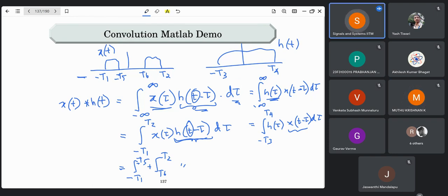You should always keep the eigenfunction reasoning in mind. The only reason that we go to the frequency domain is because the phasors or the complex sinusoids are eigenfunctions. That's all. It makes our life simpler. You don't have to do the integration in convolution at all. If you feed in an eigenfunction, the output is a scaled eigenfunction. So there is no trouble doing this integration to directly get the eigenfunction as the output. That is the primary motivation why we go to the frequency domain.